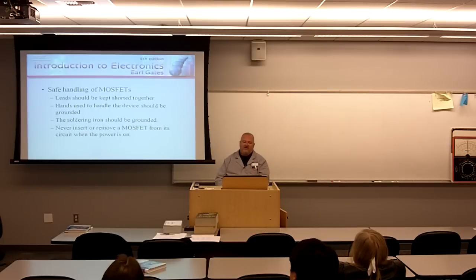Safe handling of MOSFETs: leads should be kept shorted together until you install them. You don't want to short them together and then turn the power on. Well, Joe said they need to be shorted together. No, shorted together when in transit. Hands used to handle the device should be grounded. You should have a wrist strap on. Soldering iron should be grounded. You should be wearing a lab coat when you're handling these. Some of these devices, if you just look at them cross-eyed, they're going to blow up. Okay? They're very, very sensitive. So you've got to go out of your way to handle them efficiently, effectively.